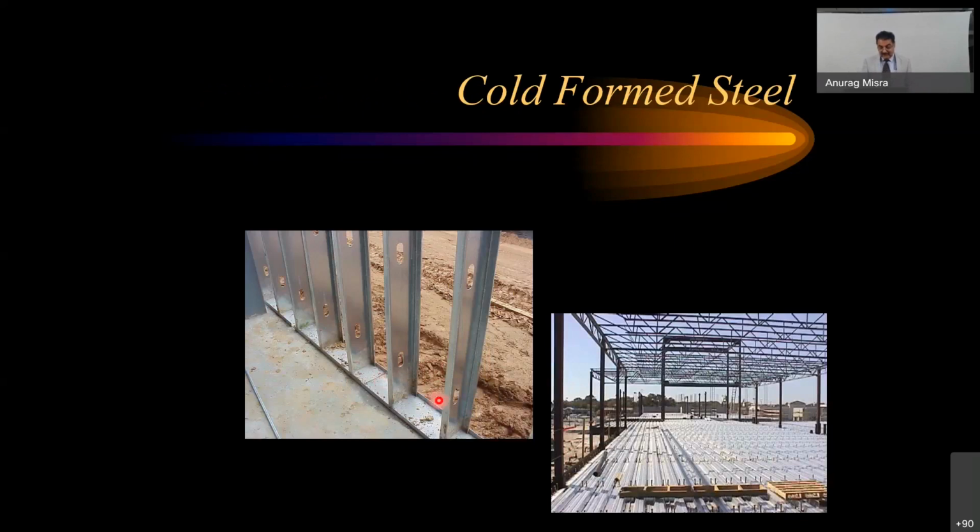These are some wall cladding being created with the help of a cold form section. You can see that there is a thin channel section at the bottom, and then some channel sections are actually put on these. So this will provide a double layered wall, which could be filled with insulation here, and also could be used for services, because you have to carry lots of pipes. Some places only electrical ones. Otherwise, you have to take some plumbing pipes as well.